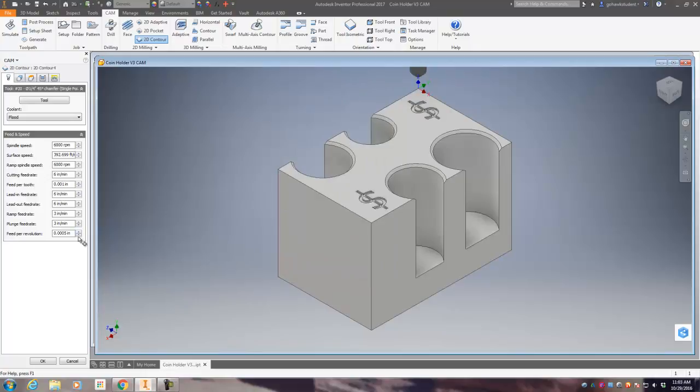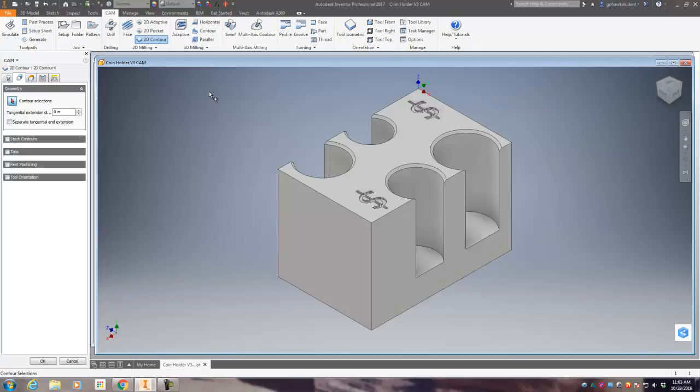Select. We'll just leave those feed rates as is. That'll be fine for this tool. One tab over. What is it that we want to chamfer? We kind of want to just chamfer this whole top of this whole part. So I'm just going to find a spot that allows me to get everything, which is here. Click it, and that's just going to go around and chamfer the whole works.